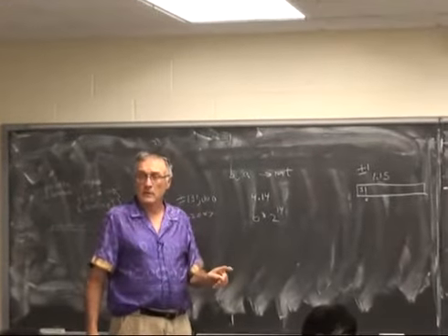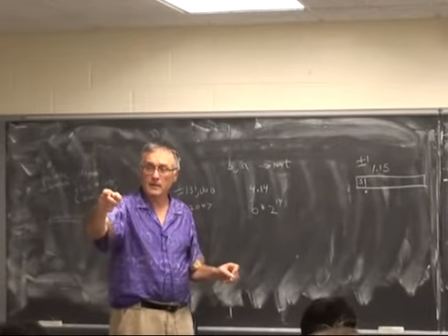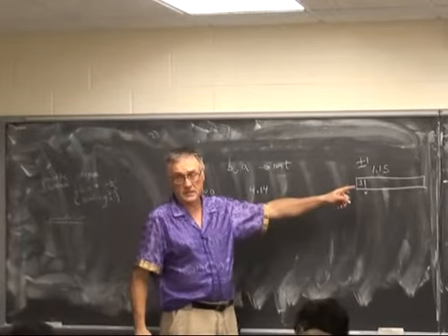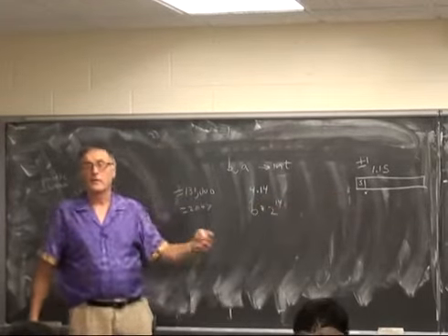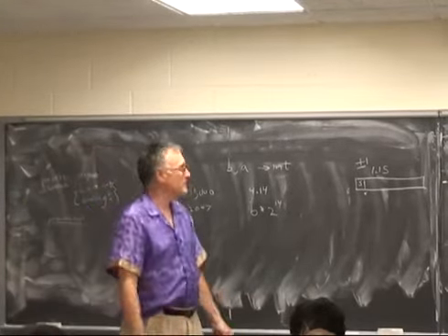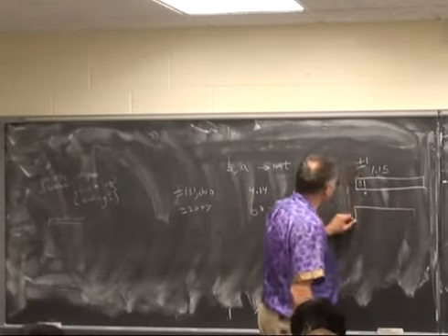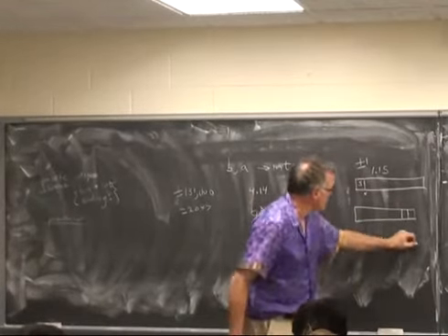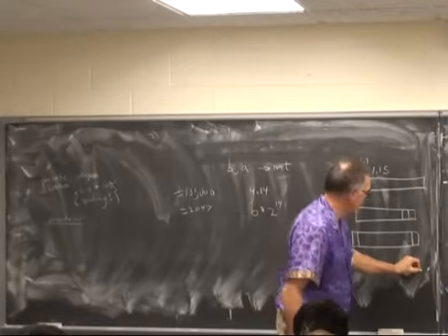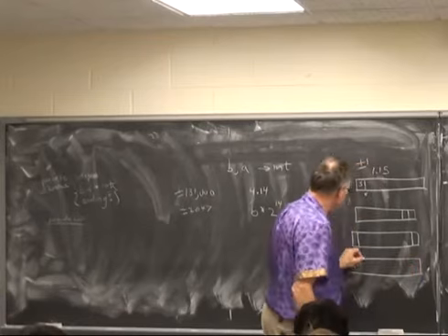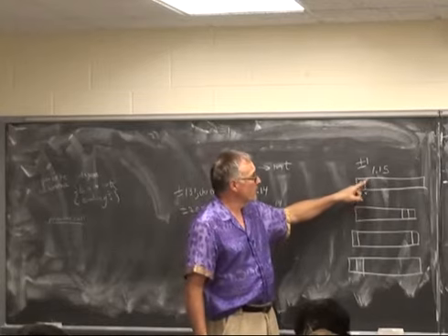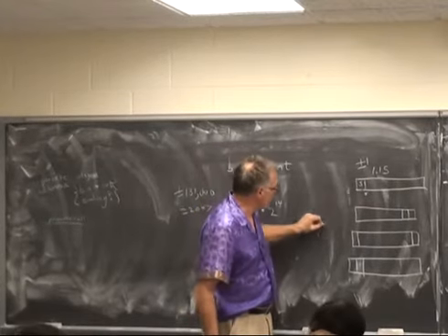Clearly, you're going to have to extend this 16-bit number to 18 bits for the CPU. You can do it in 3 ways. You could put the 2 extra bits here. You could put 1 bit here and 1 bit here, which would be odd. Or you could put 2 extra bits here to extend the 16-bit audio into 18 bits.